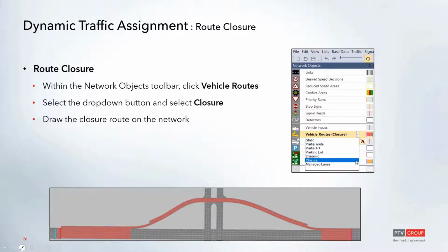And then another way is if you did a temporary edge closure, maybe closing this through edge at this point right here. And this will force another route to be found if it exists. So what you can do is just temporarily run one iteration with that edge closure in place. And then after another path has been found, you can go ahead and remove that edge closure and add in the route closure. And in that case, vehicles will then pick up that alternative route that was found and will take this route closure into effect.